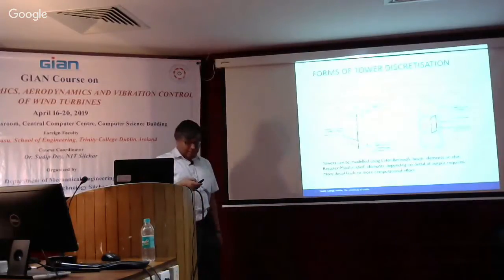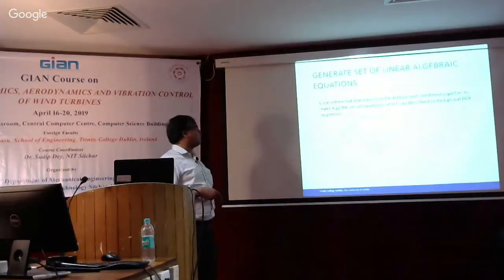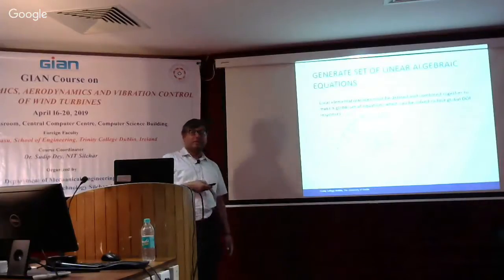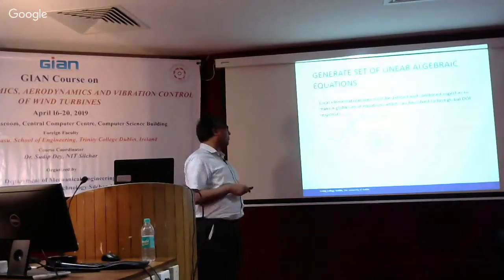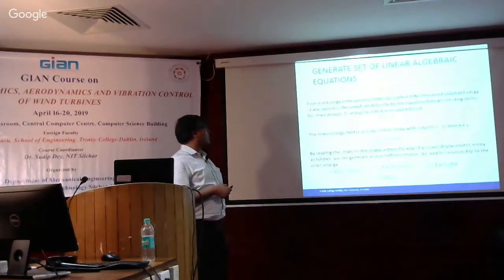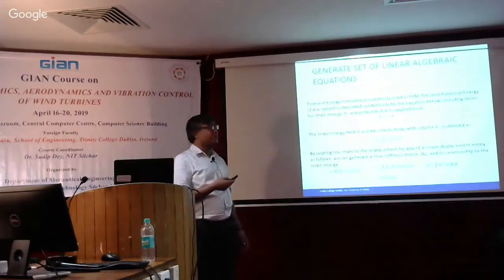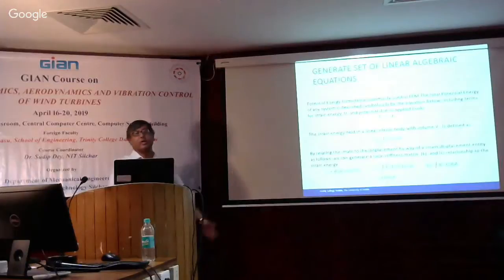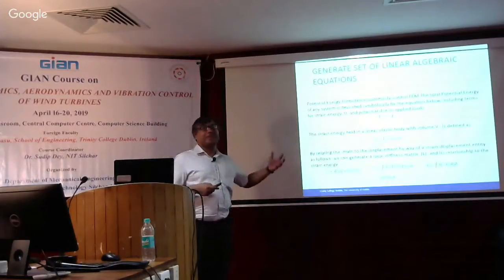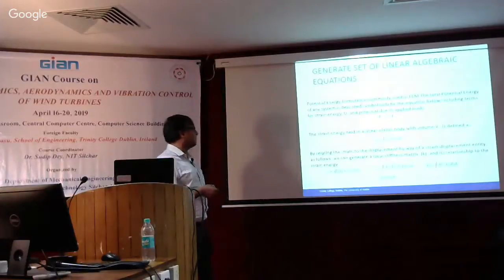and modeling. And if you do that, then obviously, first of all, you develop the local matrices, and this is what you have for the usual beam element. So you have 4 degrees of freedom per element, so it's a 4x4 matrix. And then you can have the potential energy formulation. So this is the total strain energy here, U, and obviously that is given by half epsilon transpose sigma dV over the whole volume of the system. I think this is something quite trivially known to most of you in a formal way. So this is your strain energy.